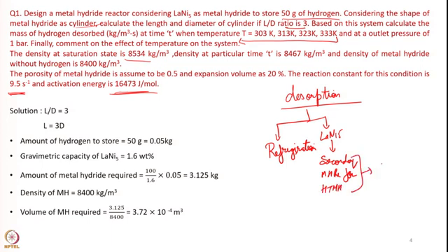This is in the case of thermal energy storage systems, which means when the hydrogen is desorbed from the high temperature metal hydride, it is absorbed in the low temperature metal hydride, and accordingly the desorption will be as fast as possible, so that more and more hydrogen is present at the high temperature metal hydride reactor, so that it will generate more heat, and that will be available for utilization for particular cases.